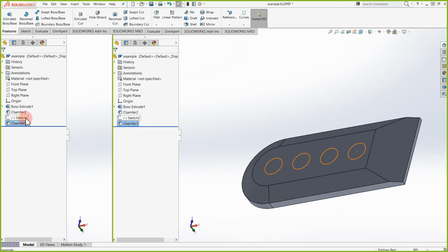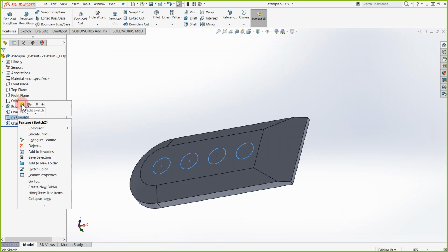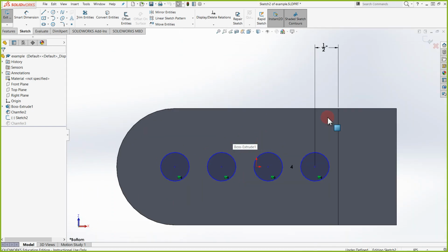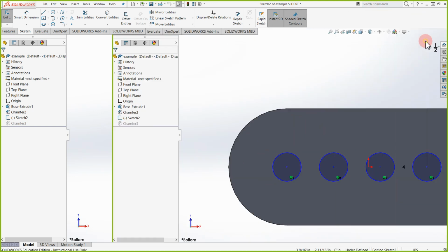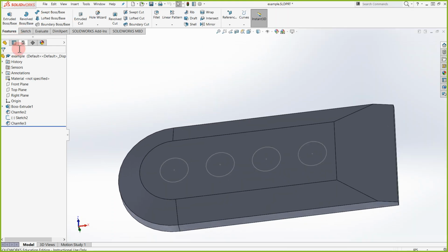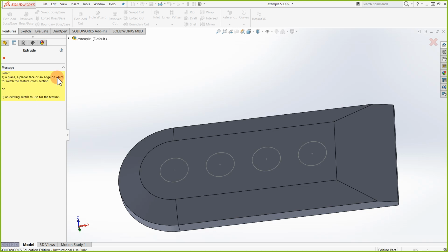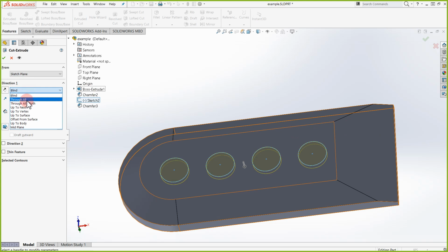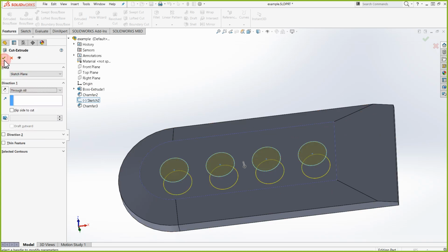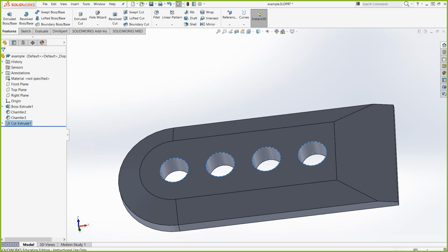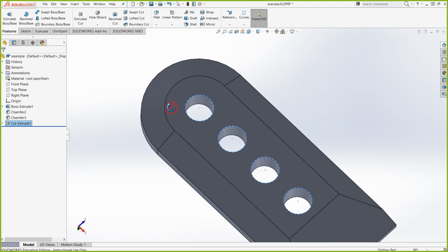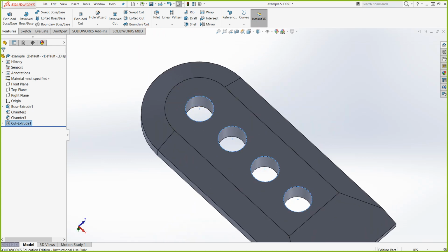And then afterwards, if we go back and edit the sketch, we see that the distance we had before, once you do the math, should be 1/2 inch from here, and then we have our spacing, and we have our hole directly perfect. All that's left to do to finish this one is just do our extrude cut. Let's do extrude cut, choose our sketch that we worked on, go through all, and press accept. And like that, we have the holes go through all, as we see in the drawing, and we have our piece that should have taken faster, but took not like a whole day to do. But we have that first piece done.